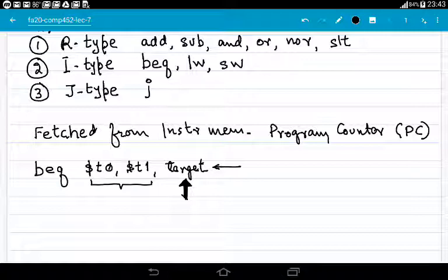By the way, this is one instruction in which two different ALUs are used. One is the main ALU, and then there is another secondary ALU that calculates the branch target. I think you remember that from our previous discussion, but I will elaborate on this in greater detail when we come to that point.